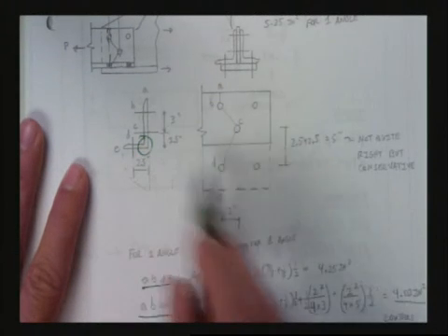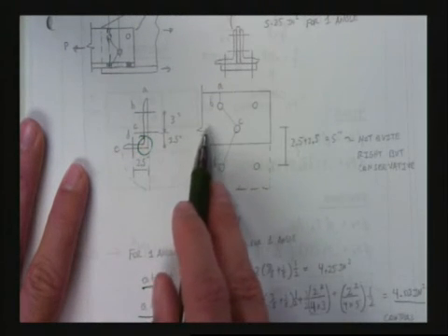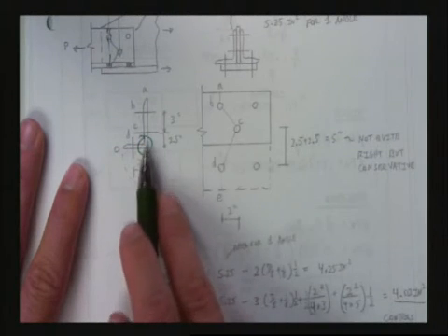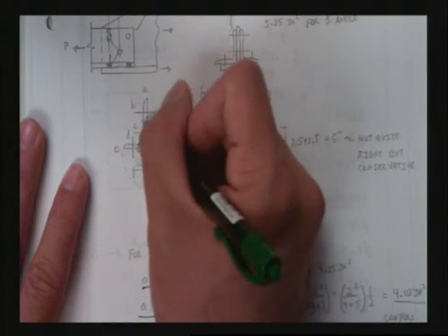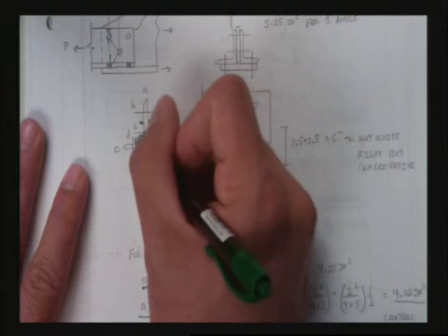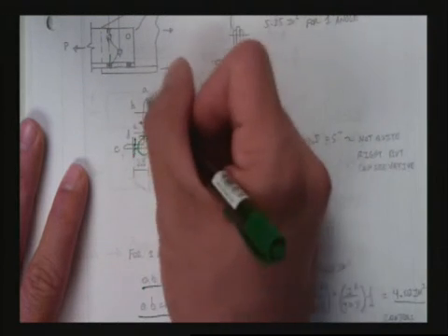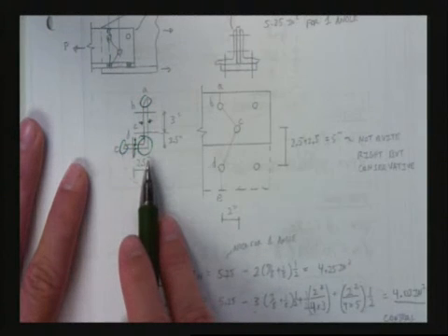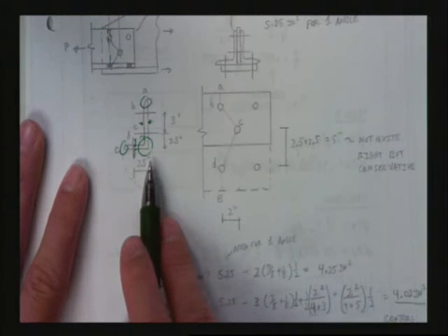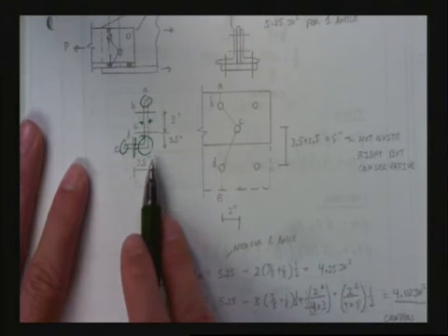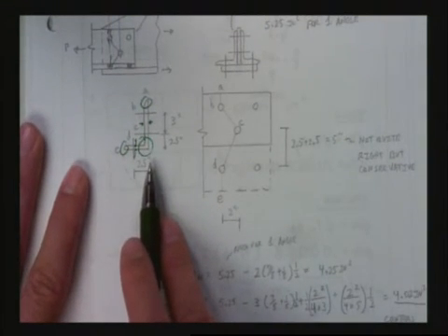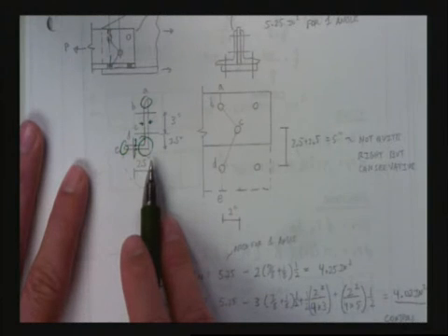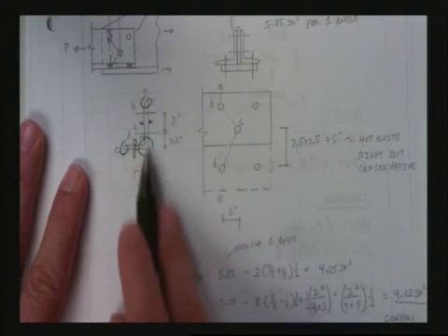When we look at the thicknesses of these plates, we'll find that the thicknesses are not constant. They're constant in this area, they're constant in this area, but they taper at the ends and they taper at the middle. Why? That's how the steel is made. That's how they're rolled. If this is a rolled section, that's how they're made. If you're using a built-up section made out of plates, it's not how they're made. They're truly going to be a constant thickness throughout.